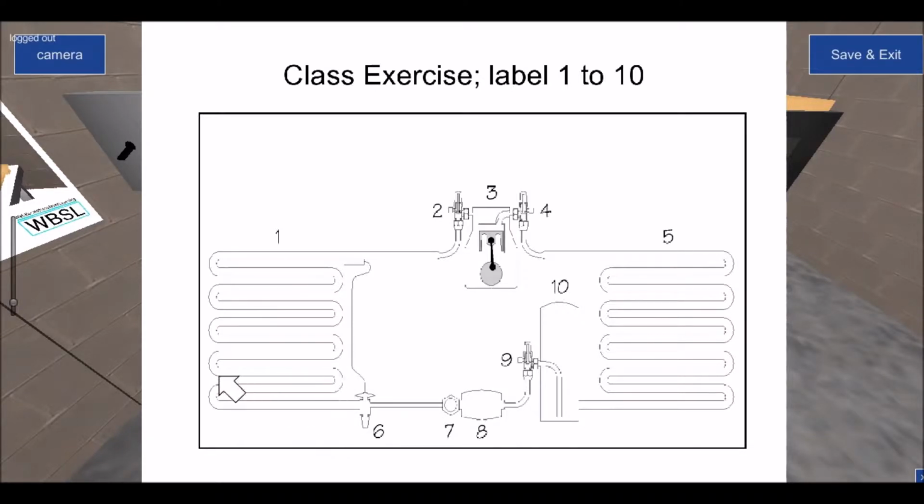You don't need to worry about flash gas for the moment. It travels through the evaporator and eventually boils off in the evaporator, so that at a given point in the evaporator it becomes 100% low pressure, low temperature vapor. It exits that vapor, enters into the compressor and continues on its way. So you just need to be able to draw the diagram and write that down, and that's what the conditions,